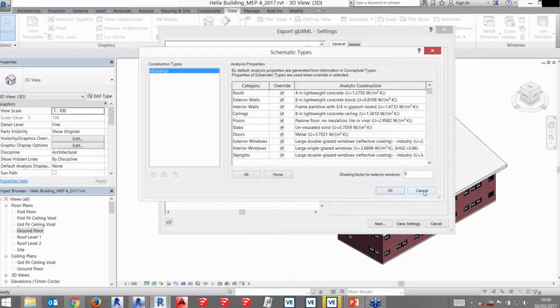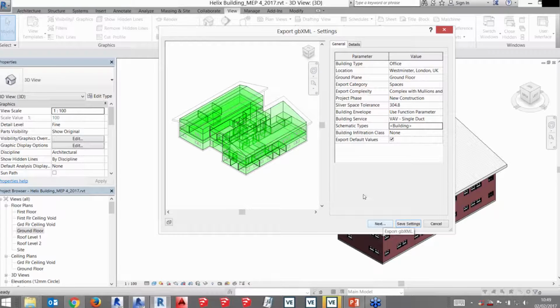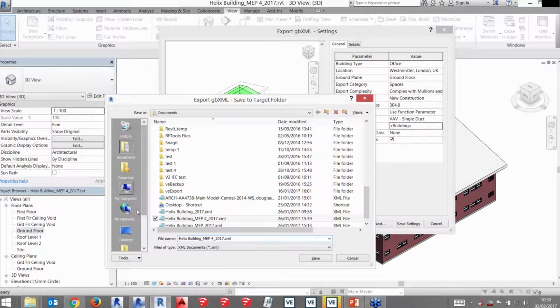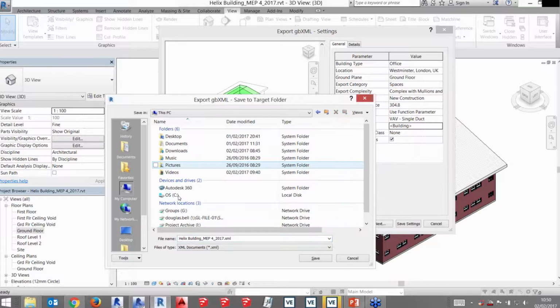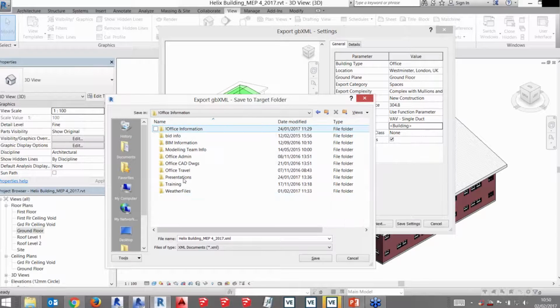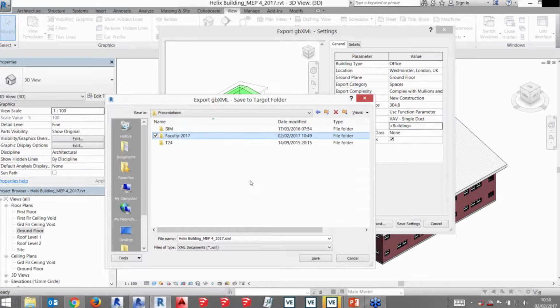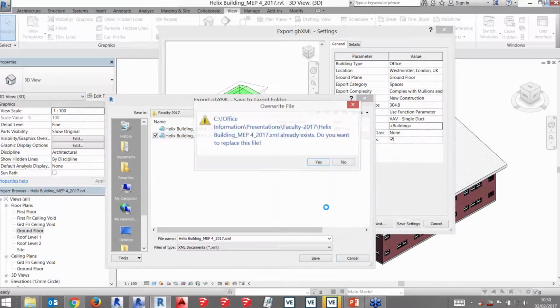I forgot to add, you need to go to, which I'll show you in 2 seconds, make sure that the detail elements option is checked in your energy settings. So I'll OK that and I'll just hit next and export that. So again, source a place that you want to place this. It's on your machine. So I'm going to put it in my folder and that's exported.